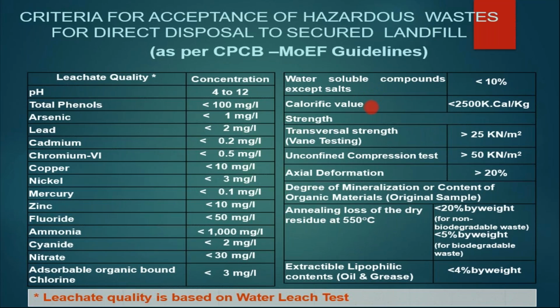salts less than 10%, calorific value less than 2500 kilocalorie per kg, then strength in terms of transversal strength when testing, then unconfined compression test, then axial deformation, degree of mineralization or content of organic materials, then annealing loss of the dry residue at 550 degrees Celsius, then extractable lipophilic contents, oil and grease.